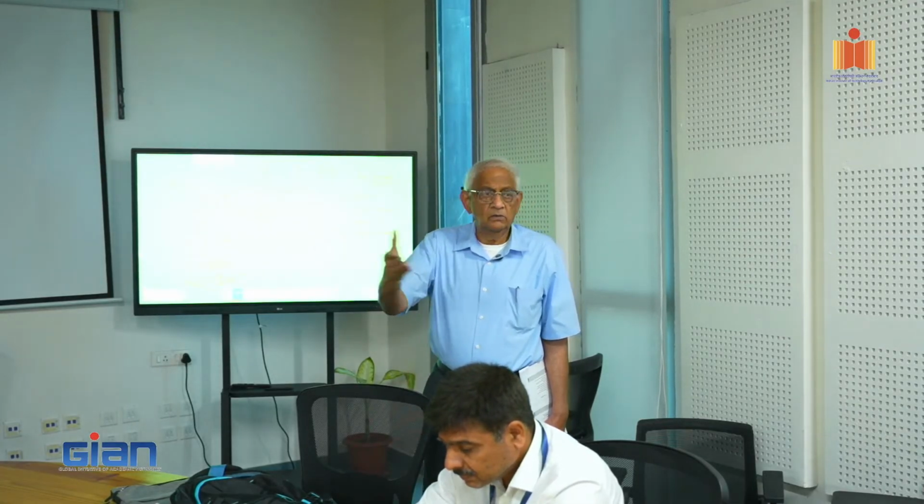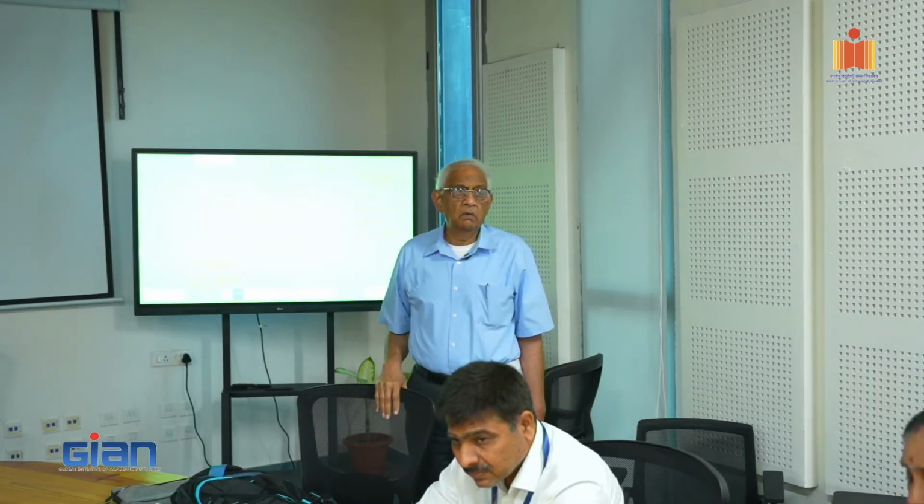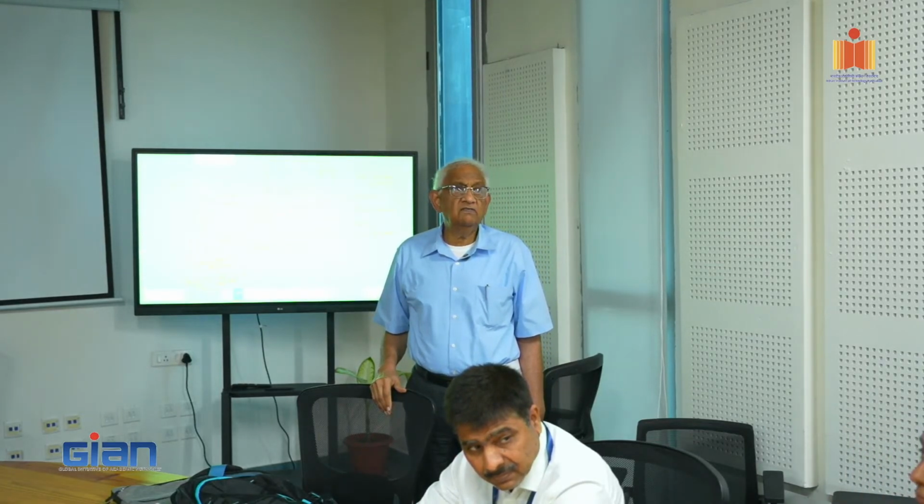Sir, one question from online participants. They are saying that with GFRP we can't maintain the site. So what will be the development length if we are using it? Well, I gave you the equation for development length. Please follow that. They're all in those 300 slide package. Those are very valid. If anything, they are on the very conservative side. In other words, even if you reduce it by 20-25%, you're doing well. Primarily focus on the development length only on the tension side. Don't have to worry too much about it on the compression.